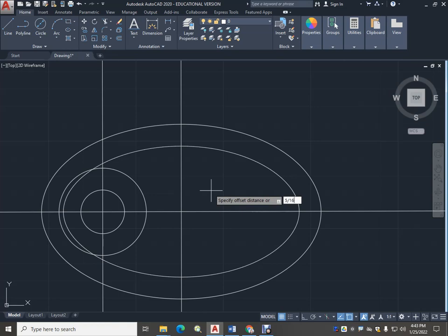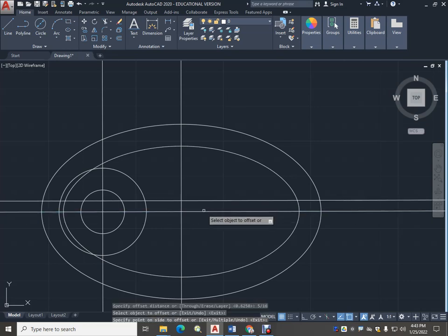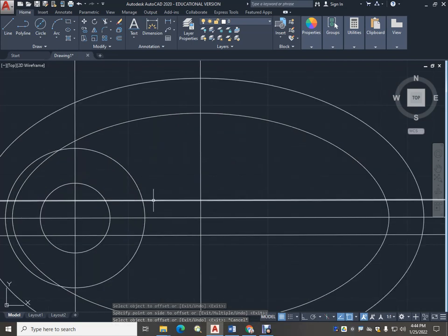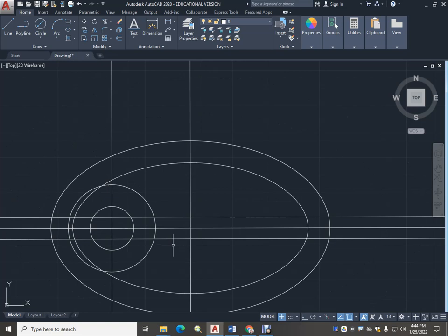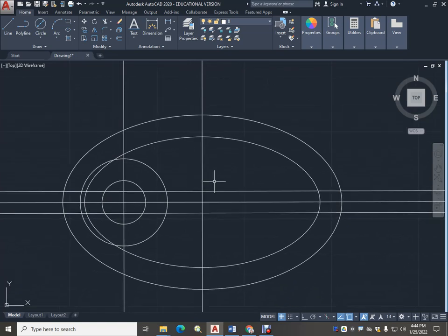5/16 would be the half. Hit the space bar. And that would be the centerpiece that we would need. So we'll have the ring, the centerpiece, and now these are open spaces. Anytime you have sharp corners on a part, like here and here, those are always our weakest positions. So we like to put fillets in there, and as we put this fillet in, it creates a much stronger part, because anytime there's a corner, here's where it really likes to go.